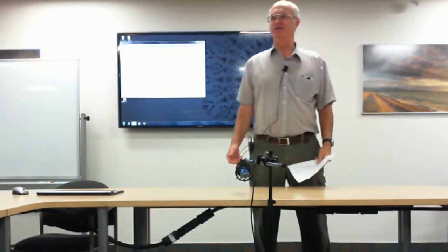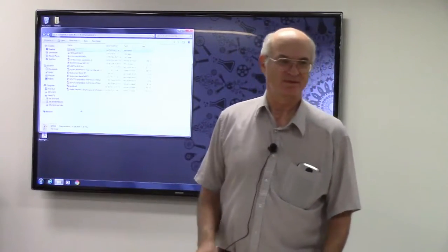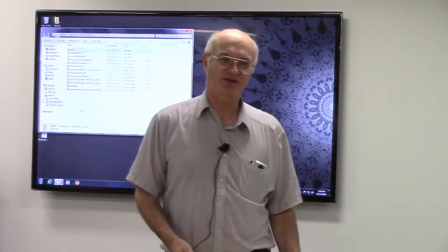So as I was saying, to eliminate interference, you either have to get it at the source or get it at the device that's being affected. It's always best to get it at the source if you can, because if you get the source, that takes care of all the devices. If you have to go to the device that's affected, then you have to go to each and every device.